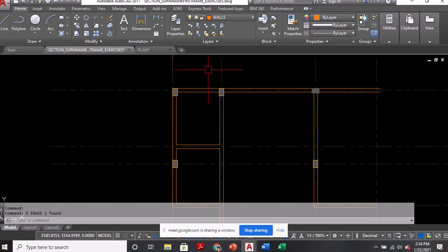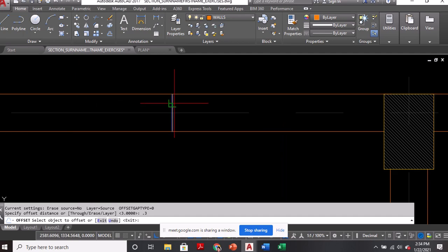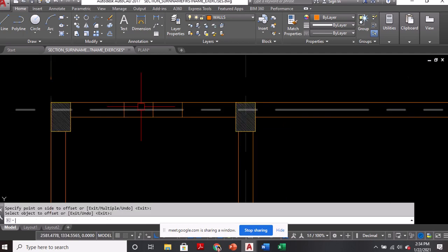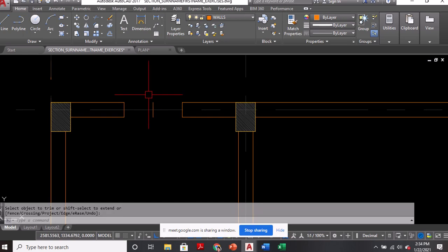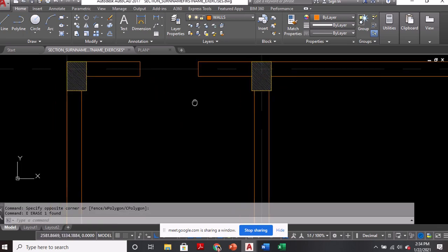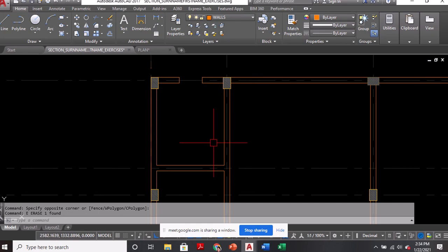So, we have to create the opening first. I have my layer wall. I'll snap midpoint to perpendicular and offset this at 0.3 on both sides. Okay? So, bakit kaya 0.6 lang? Kasi yun nga, maliit lang, privacy purposes. And under the National Building Code of the Philippines, the minimum area for fenestration is 10% of the floor area. Okay? So, ilan yung area nito? So, minimum nun para dun sa opening niya is 10% of that entire floor area. So, you have to compute.